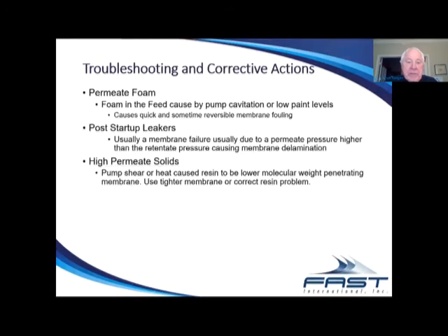And then high paint solids, this can be caused by shear, heat, or whatever that may have lowered the molecular weight, allowing it to penetrate the membrane. And there are tighter membranes out there that can be used to correct the membrane problem. Next slide.